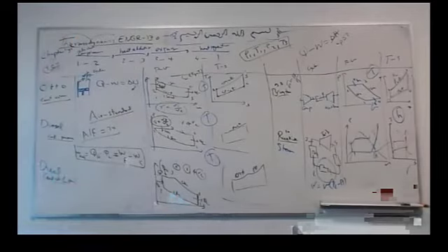Professor, I have a question. Go ahead. When we're finding the thermal efficiencies in terms of R, is that considered for ideal cases? Yeah, usually in these problems we assume reversible, so they are all ideal, but the most efficient one is Carnot, which is isothermal. We have compression and expansion as isothermal cases, not isentropic. They are ideal, but not the most efficient. You cannot say 1 minus T3 over T1, for example, it's not going to work, or the opposite, 1 minus T1 over T3. That's your question? Yes, thank you. No, it's not like that. This is not Carnot. This is reversible, yes, but not the most ideal.